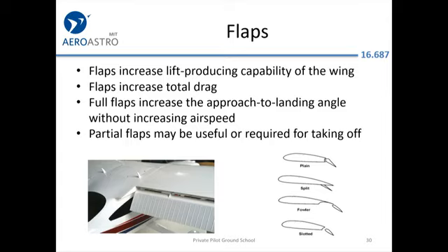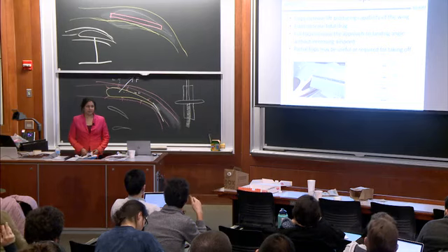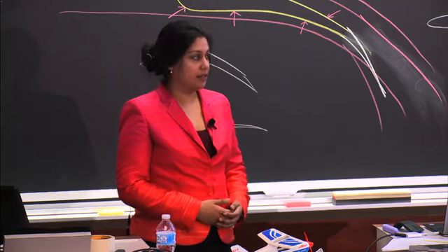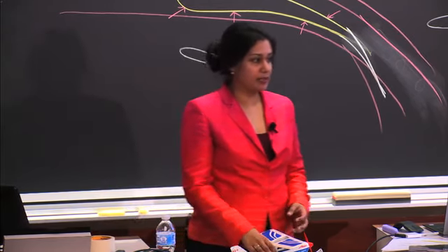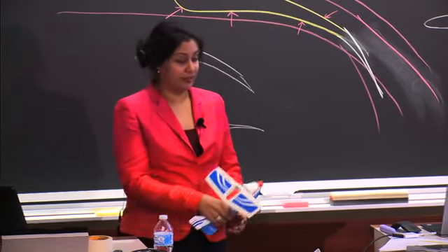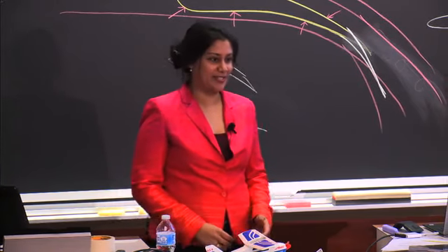So we talked a little bit about flaps, that flaps actually can increase the lift that you're able to produce, but it's a trade-off because it also increases the drag. So when in the course of the flight, takeoff, cruise, or landing, when do you use flaps? Does anyone know? Takeoff and landing. Yeah, especially on landing, many times people use flaps on takeoff as well, but the reason is just that you like to have your aircraft configured that in case you didn't take off, you can land without making a lot of dramatic changes.